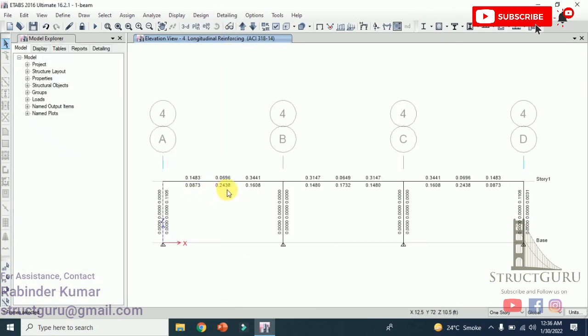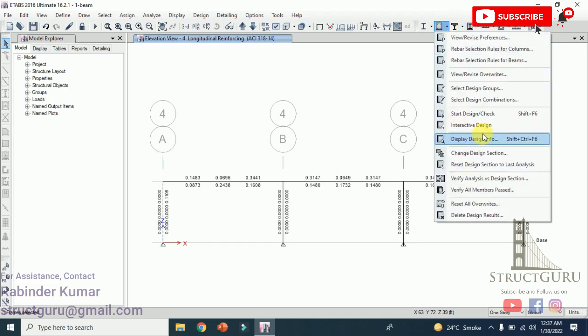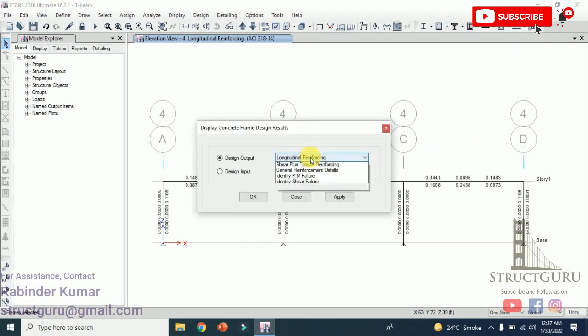So for bottom reinforcement we are getting 0.243 as a mid, okay, for first and third span, and 0.1732 for the middle span, and for the top reinforcement it is 0.064 and 0.064. If we compare it with the percentage of steel, it will give us a clear picture.